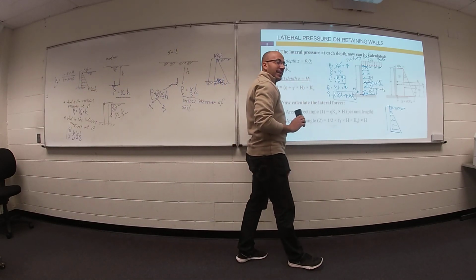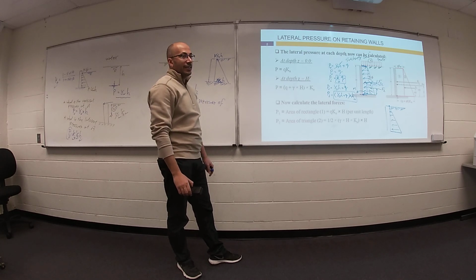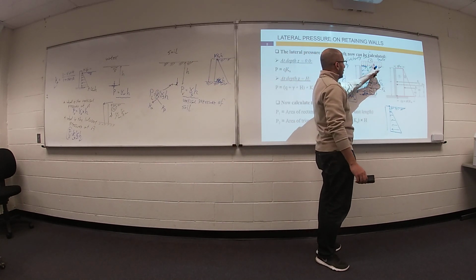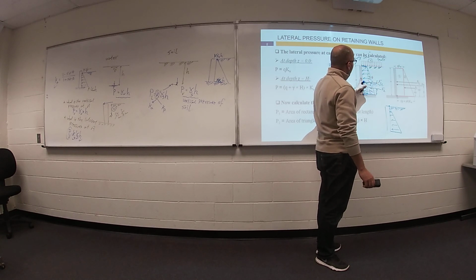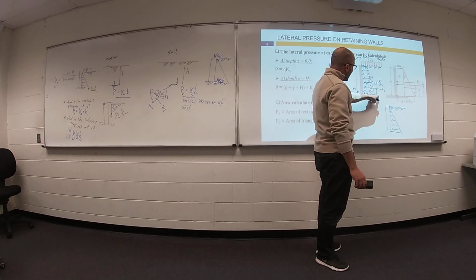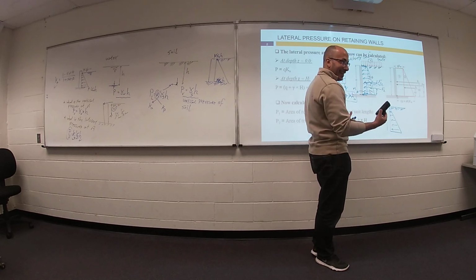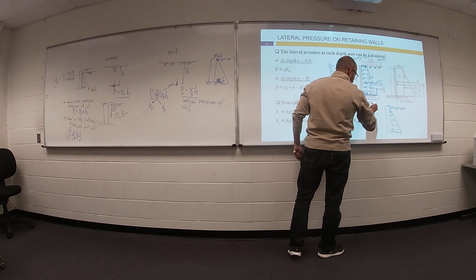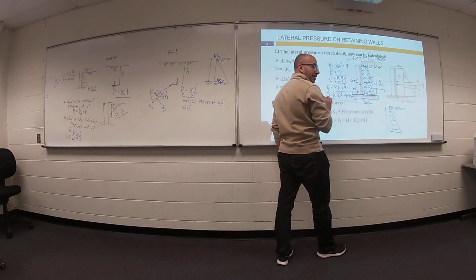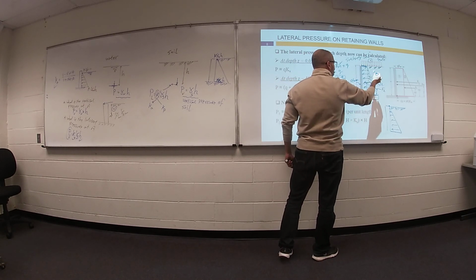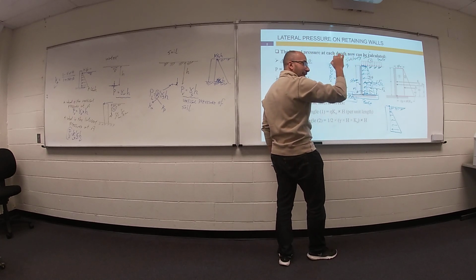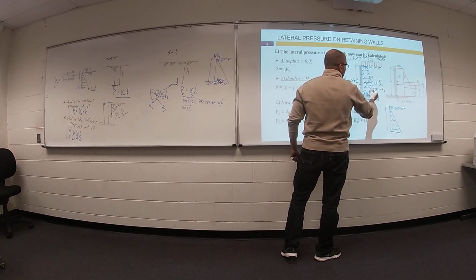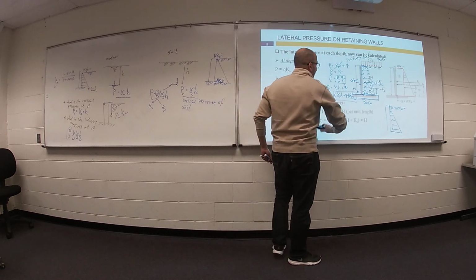Dr. Amy, can I ask a quick question? Yeah. Does the force help or hurt? Like the surcharge load, does that hurt or help the retaining wall? This load and this pressure will hurt this part of your retaining wall, but will help this part of the retaining wall for stability. We have two parts, actually: your retaining wall has a base and a stem. I'm talking right now about this part. What is the effect of the soil and the additional load on this part? Later, we will talk about the stability of the retaining wall as a whole. So we are talking about this part. Step by step.